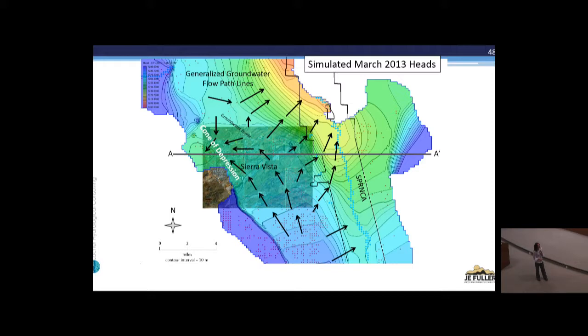So what's happening now is there's a groundwater divide. Remember that divide term. We've created an artificial divide here by pumping on this side and interrupting natural flow that would have made it to the river. So we're intercepting natural recharge here that ordinarily, under natural conditions, would have discharged at the river. We've got a new discharge point, and that affects the flow lines.